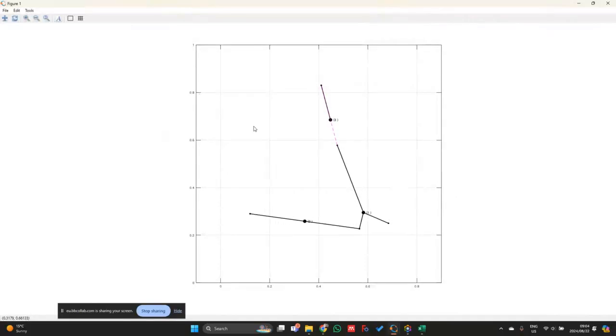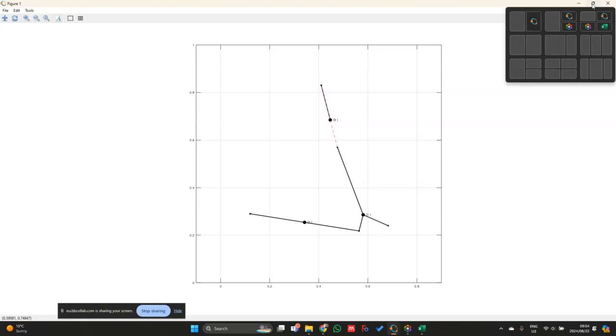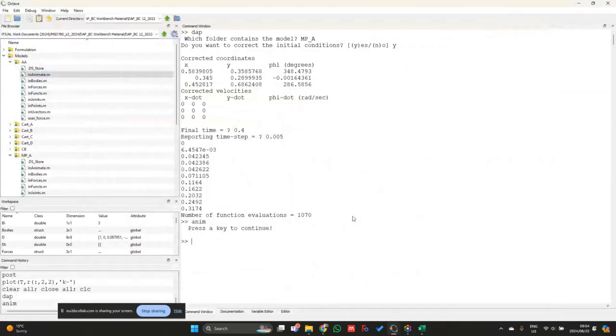Right, so now we can once again see that initial downward motion because the tire is not in contact. And once it reaches the contact point, then the spring and the damper effects of the tire are going to dissipate that y coordinate motion. And then we expect to see this constant position case over here. Right. So once that is done, I can then go and run post.